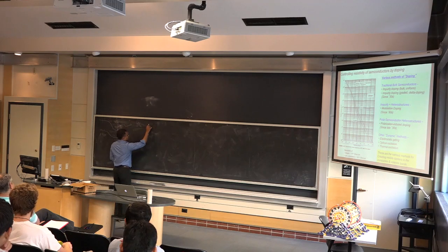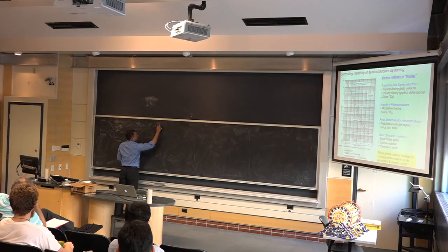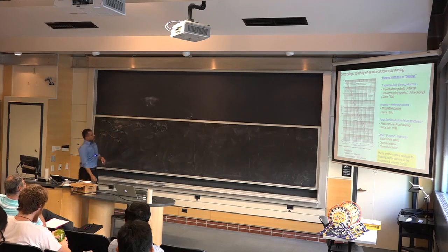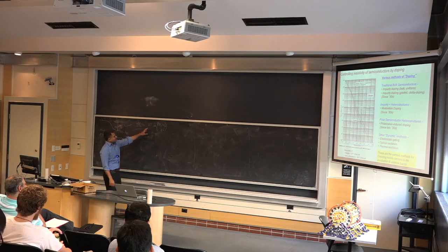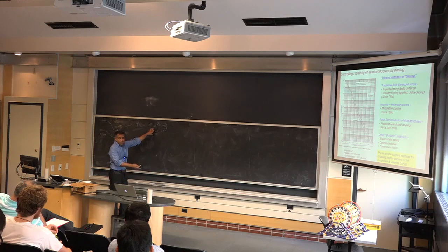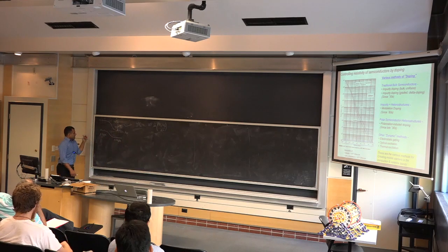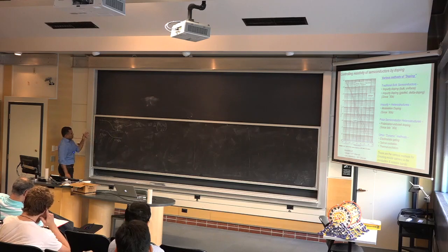We found that that's essentially given by the thermal energy, kT, natural log of the doping densities on the two sides divided by the square of the intrinsic carrier density. Such relations are obviously very useful, because on the right side, you know everything. You know how much you dope, what material you chose, so you can calculate this right away. And today we're going to develop strategies for drawing a lot of the band diagrams